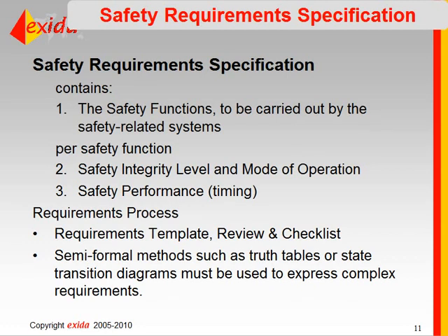So this applies to SIL 3, and this process overall that we are talking about does apply to SIL 3, although many of the same concepts apply to the different SIL levels. One of the main ways the standard differentiates between these different safety integrity levels is that most of the requirements in the standard are common to all of the levels. However, the level of rigor that you must implement to meet various requirements is more rigorous for the higher SIL levels than others. So semi-formal methods are an example of something that's generally required for SIL 3 and higher.